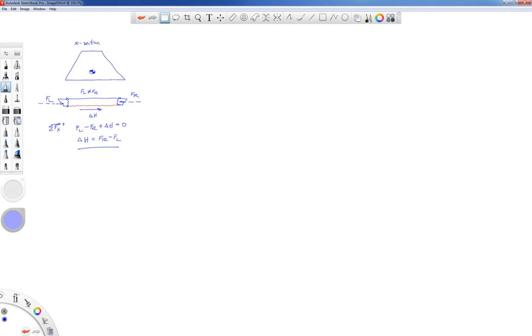In order to find this, we're going to do an integral, and the force on the left, F sub L, then is going to be an integral over some area, we'll specify it in just a moment, of that bending stress, sigma x dA on the left side. The area that I'm talking about on the side view is from this red line up to the top, but on the cross section is where we can really visualize the area.